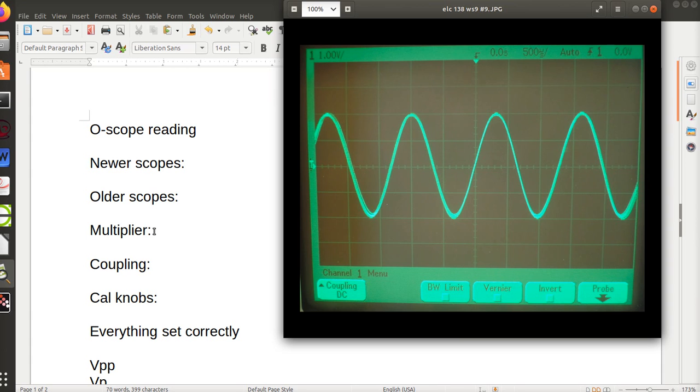The other option on that probe is ground, and that is for zeroing the signal. So you won't typically use that setting for measurement. Like never. You'll never use that setting for measurement. So your multiplier should be 1-to-1, and I suggest you start out 1-to-1. And you've got to make sure your probe is set for 1-to-1 or your vertical readings could be off.